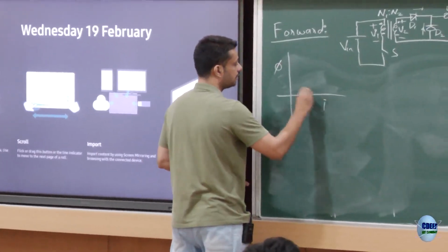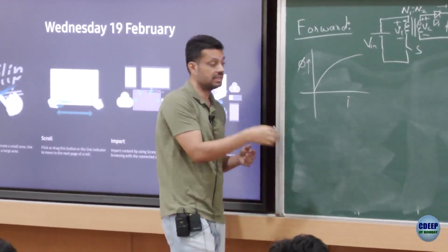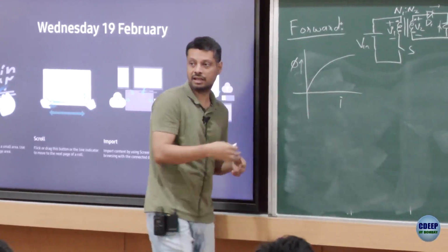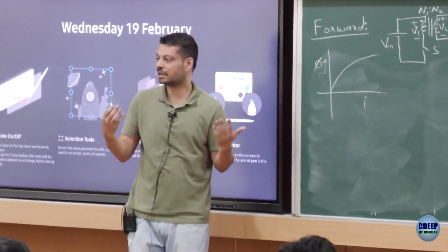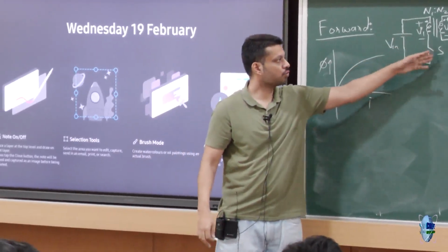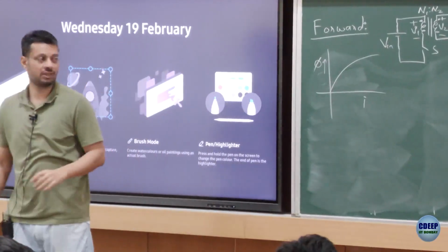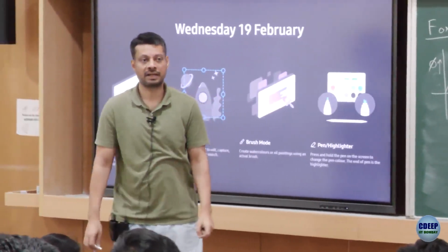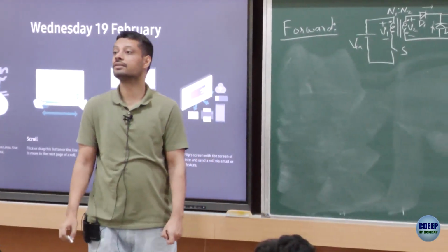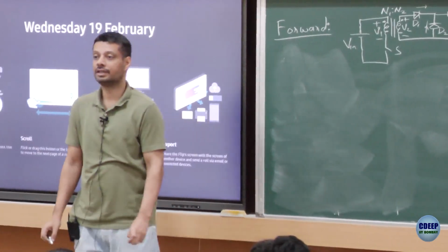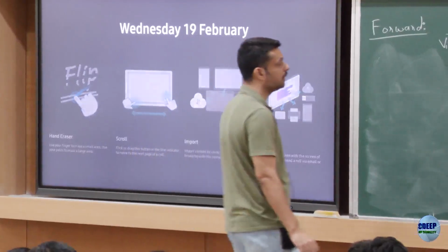Flux versus current, it's like this. So if the flux is rising linearly with a constant DC voltage, the current will rise exponentially, and sooner or later your circuit will just reach its capacity. Huge current flowing here, the switch may burn, the source may not be able to supply, something or the other will go wrong. So this circuit cannot work in practical conditions, right? Is that okay? Any doubt so far? Any suggestion? Okay, so what do we do?